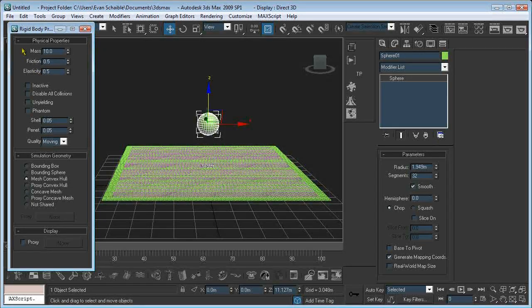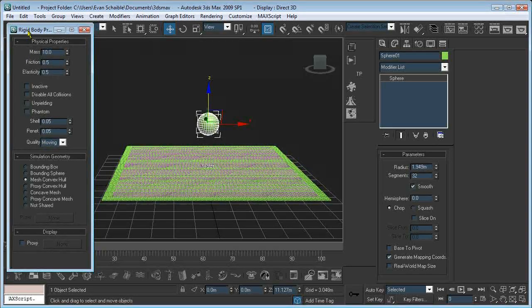Now, within the Havok system, physically accurate settings are usually between 0.1 and 1. And if you go out of that range of settings, you'll get warnings from Havok that tell you you'll get physically inaccurate and unrealistic results from your animation. But unless you're going for a certain specific effect, it's not really beneficial usually to go outside of that range. But for this demonstration, we're going outside of that range, and we'll probably be outside of it for the most part. So our mass is set at 10, and if I create an animation at this point,